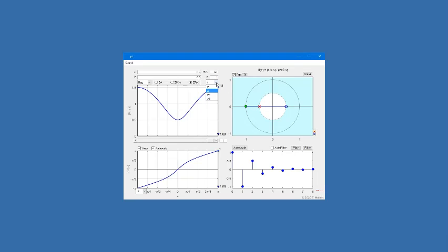And finally, you can show the contributions of everything. Here's the pole, here's the zero. This is the constant k here, and the dotted line is the product of all of these traces. The little 0 button sets the angle of the bug back to 0.